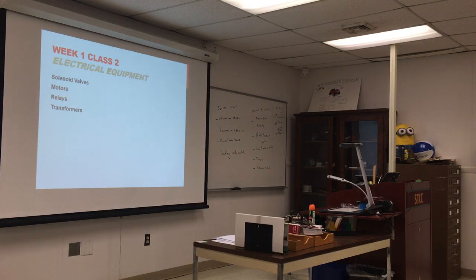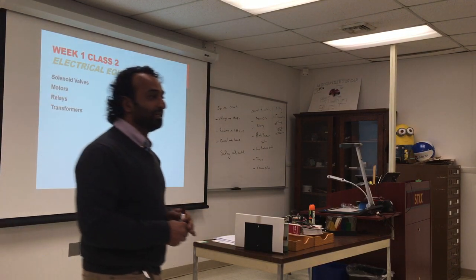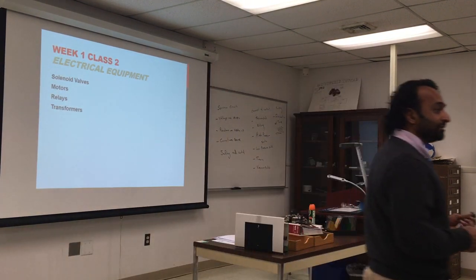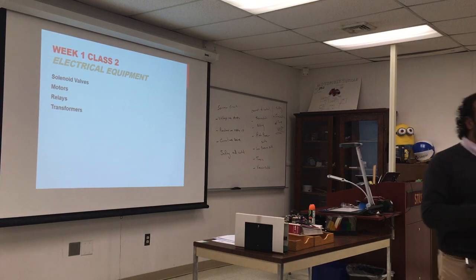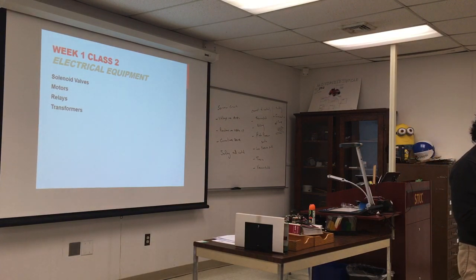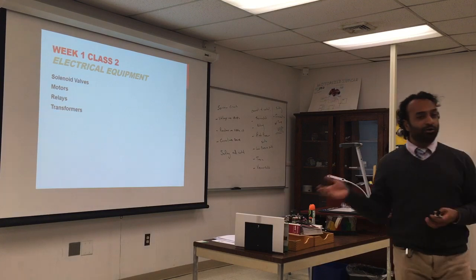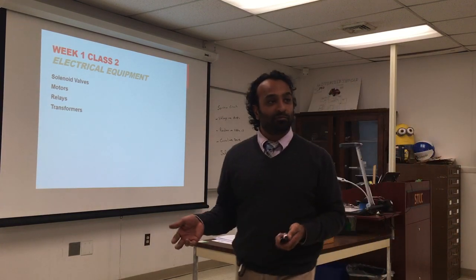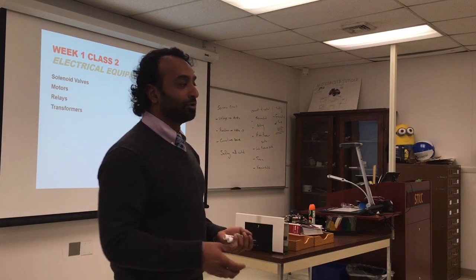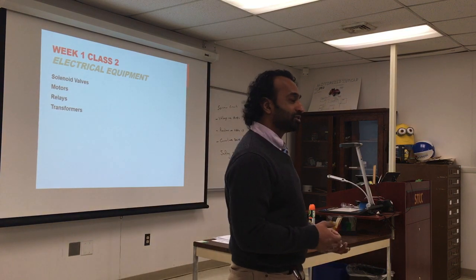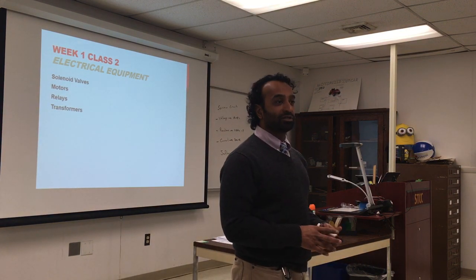So mostly nitrogen, and oxygen is 20%. Remember that, because when you do the combustion testing, you have to measure the oxygen. If you have less oxygen, it means you are burning the oxygen, which is your goal. It's very difficult to burn all of the oxygen. You're going to burn most of it. So 15, 14%, that's pretty good. How much oxygen do you think you take with each breath? Not a lot.